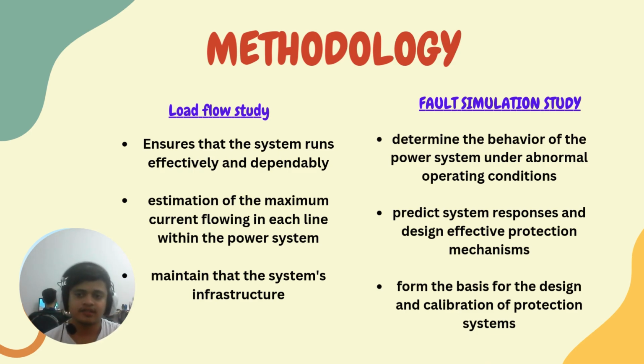The result of the load flow study then forms the basis for the design and calibration of protection systems, especially overcurrent protection. Load settings must be cautiously selected in such a way that there is discrimination between normal operating and fault conditions, reducing to a minimum the possibility of spurious trips, while ensuring a trip on fault occurrence if required.